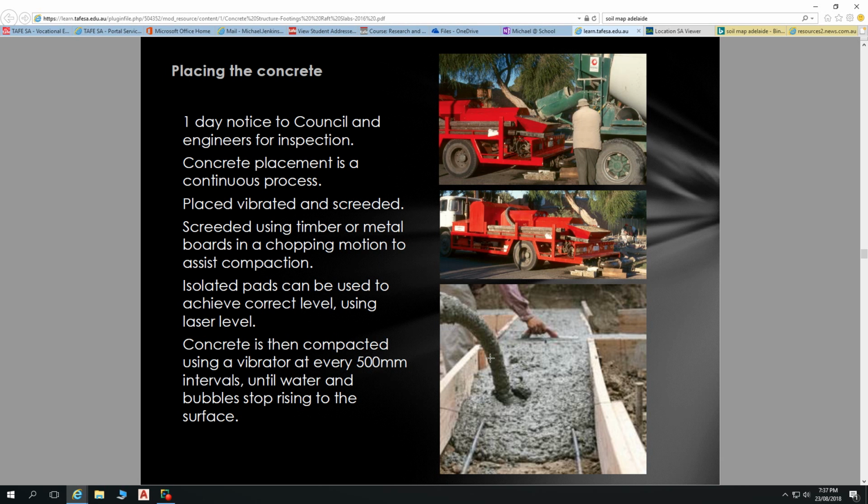Concrete also needs to be vibrated when it goes in. If it doesn't get vibrated, it gets air pockets in there. Pockets of air make the concrete weaker. It's a point where there's no structure to that concrete. And so that vibration of the concrete happens with this vibrating pole that just gets shoved in. It's driven by a two-stroke motor, and it's shoved in there and vibrates all the air pockets up to the top.